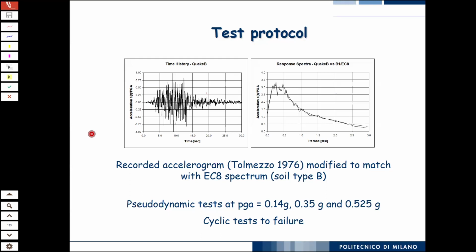Because the interesting thing is that since these structures are very flexible, and the columns, as you have seen, have plenty of strength, if you compute the theoretical earthquake resistant capacity, they can resist earthquakes up to 1 g. What does it mean? It means that you have the building with its own weight, put it like this, and it will resist its own weight, but acting as a cantilever. So it's not common.